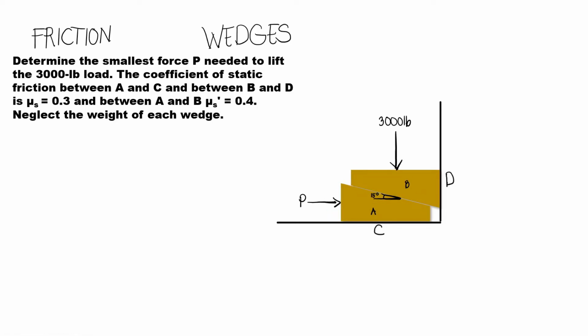And so now we will be able to determine the direction of friction because our frictional force always acts against the movement of the body. And then for this part right here, if we go back, we have different directions in our frictional forces because for this block, the movement is toward the right. And so to resist that one, we have a frictional force here and also here, considering this block. However, considering this one, we have a normal force here. And if we have a normal force here, then something should oppose that one. And so for this block, our frictional force will act this way because the horizontal component of this one will counteract the normal force. And so that's essentially the direction of our frictional forces.